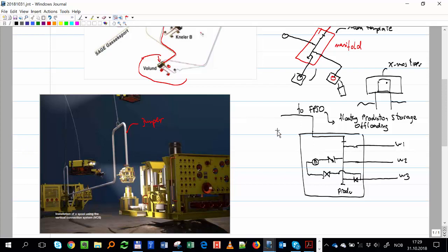Okay? So I have almost solved the exercise for you. But you have to do it also for the other wells. So you don't need to have just a line, but you need to have another header. That will be the test header. So just keep in mind this small clarification: you not only need a header if you have two lines and two separators. You can also have two headers for all kinds of reasons. For routing, for metering, for all kinds of things.